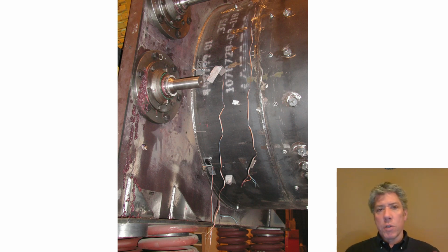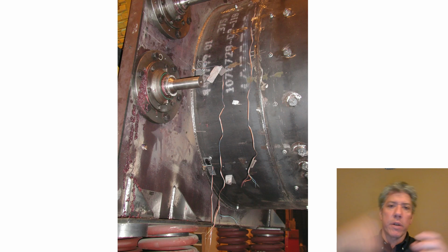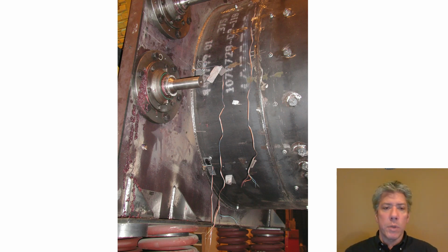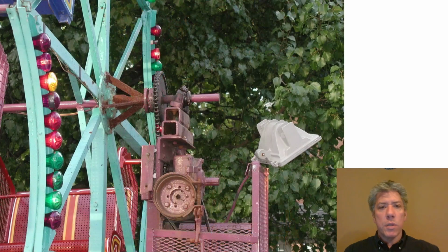These are very large machines. The springs there are probably 8 to 10 inches in diameter, so these bearings are actually very large. You can't really see it, but there are some offset weights, and the bearings have to support these weights as they are slung around on a shaft. That's what causes the shaking motion of the machine. So the bearings take a beating on these things, and you can see these have been filled with grease, and either the grease has leaked. I don't think this machine failed because it doesn't look like it's been painted yet. It looks like just a sloppy job with the grease. I'm really not sure of the story behind it, but these are fairly large bearings being put into place on the machine to support the shafts.